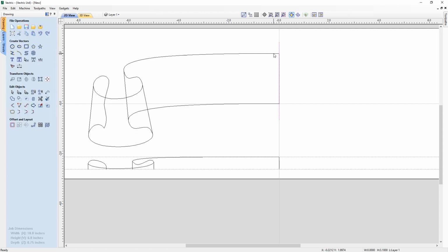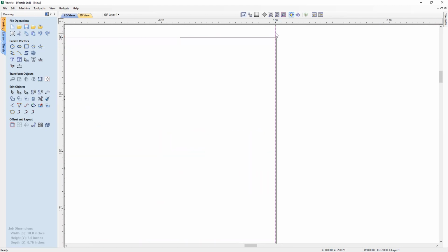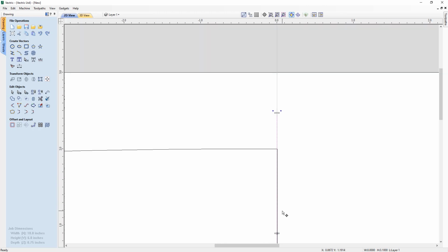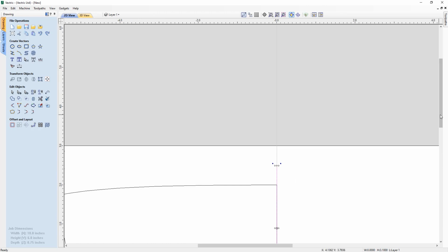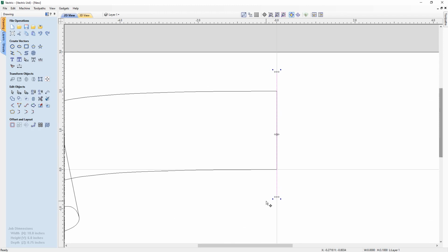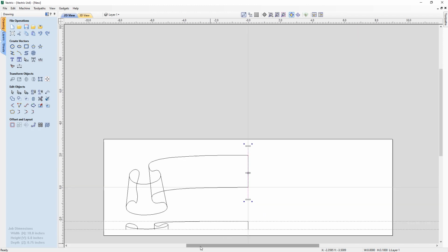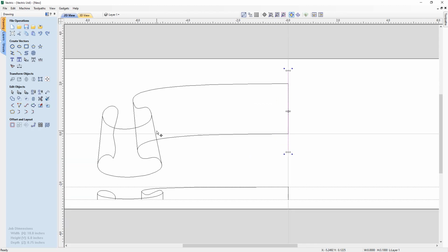And remember back when we drew this, I actually extended this shape out a little bit. Well, make sure that you pull out that vector just so it lines up nicely on top of there and snaps on there. There we go. Okay, so it's overshooting that just a little bit. That way the component that we create, when we mirror it across, will merge in nicely like it should.